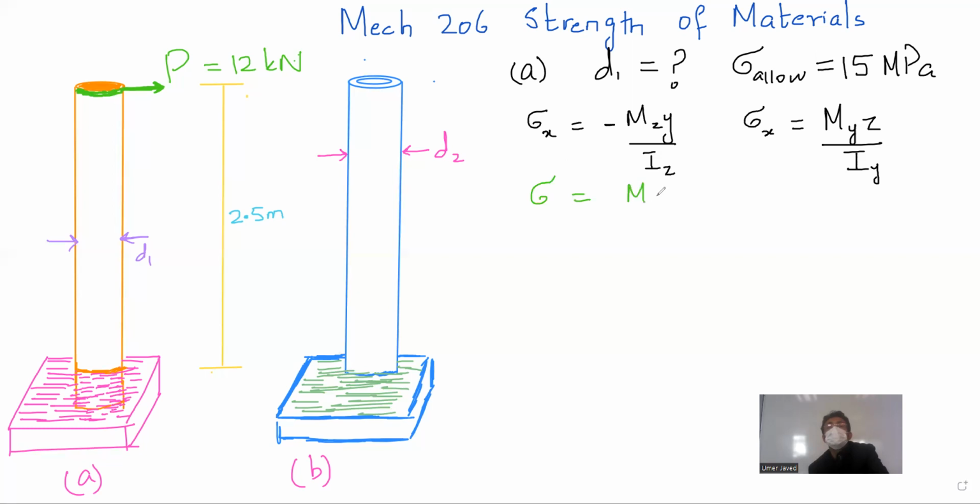Stress is equal to M C over I. How many students agree? Can you all focus here? What did I do? I just wrote it MC over I. What is C? Now, C, no, this is what I'm about to tell you. C has always been denoted as radius. From here onwards, I will denote C as the maximum distance from the neutral fiber.